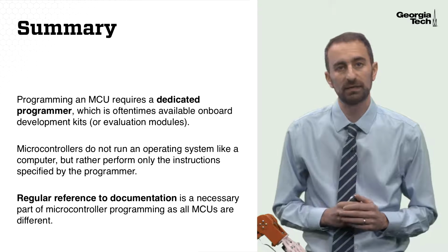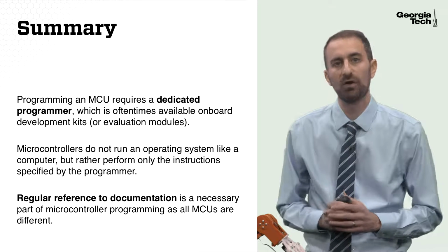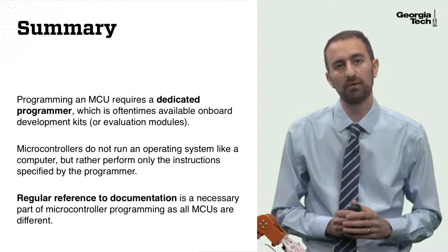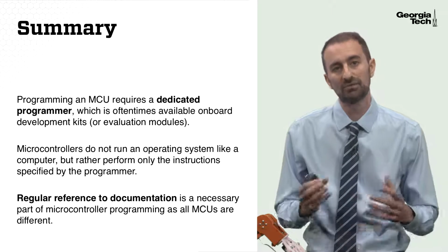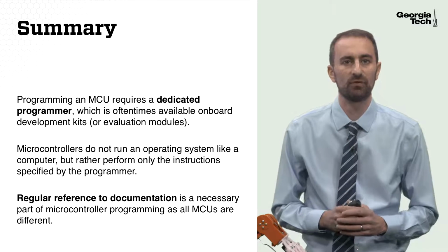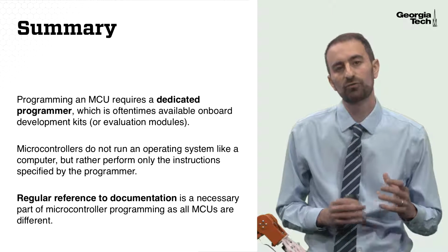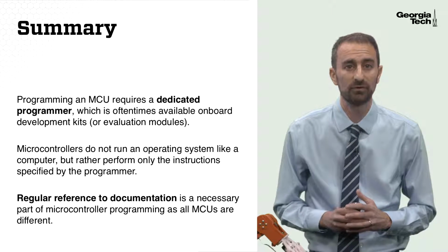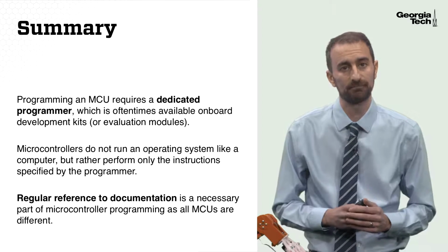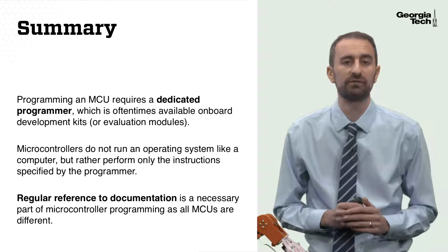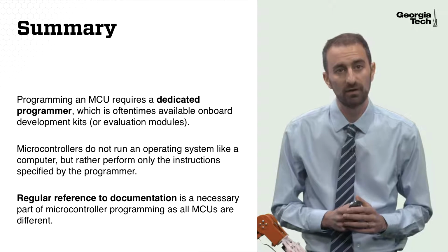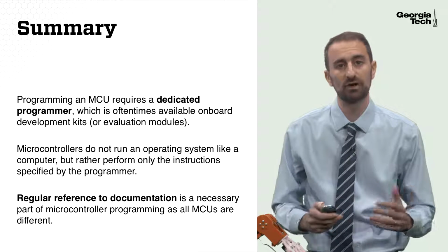To summarize what we've learned in this lesson, first, programming a microcontroller requires a dedicated programmer, which for development kits or evaluation modules is oftentimes on board the circuit board itself, and allows us to program a microcontroller from our computer. But in general, programming an actual microcontroller integrated circuit requires a dedicated programmer. Microcontrollers do not run an operating system like a computer, but rather they only perform the instructions that are specified by the programmer. Finally, regular reference to documentation is necessary and is a key part of developing software for microcontrollers for any mechatronic device that we want to build.